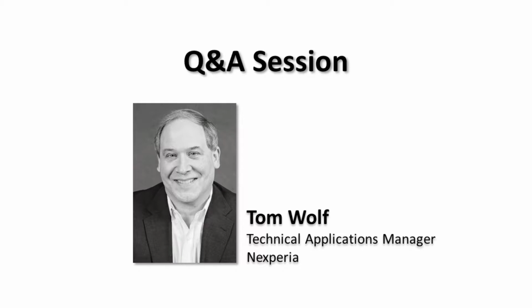Very briefly, Nexperia uses a different physics, a different topology in our design. We use a superjunction structure instead of a split gate, which most of our competitors do. So we build parts with some of the widest SOA in the first place, and have the ability to stay in that linear range for much longer than traditional designs. So hopefully I've answered that question. If not, please send it again and we'll make sure. It may take more than the time we have here to get into the details of that specific question.